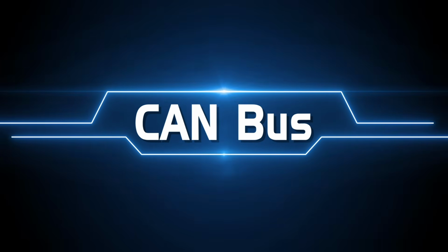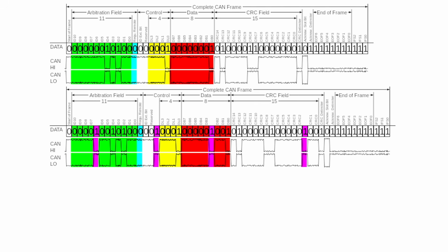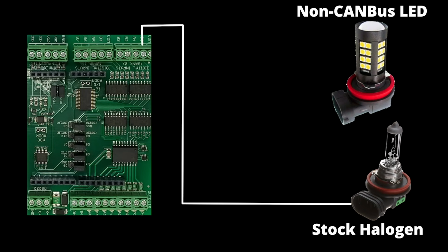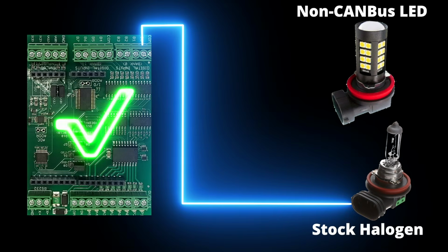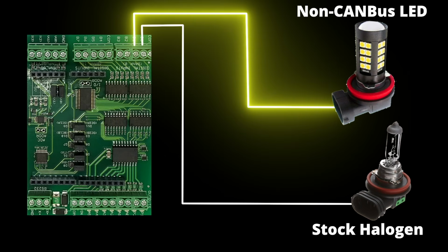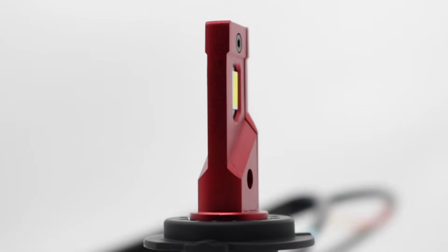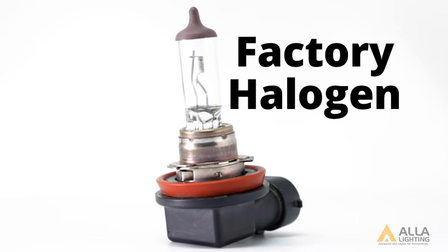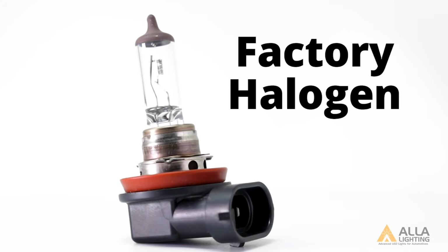First, CAN-bus. CAN-bus is the system that newer vehicles use to communicate with each part, not only to send out instructions, but also to monitor if each part is capable of performing what has been instructed by checking the value of the current running through each part. Second cause, the characteristics of the LED, light-emitting diode, differs from the filament, resistor, in an incandescent bulb.